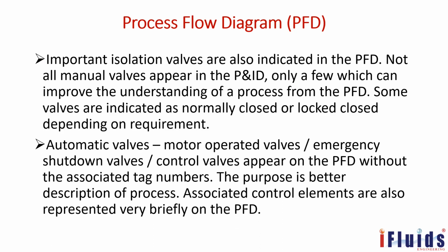Important isolation valves are also indicated in the PFD. Not all manual valves appear in the PFD, only a few which can improve the understanding of the process from the PFD. You have to show all the important valves: all control valves, shutdown valves, even a manual isolation valve if it is a very big, important valve. Small isolation valves and drain valves you don't need to show.